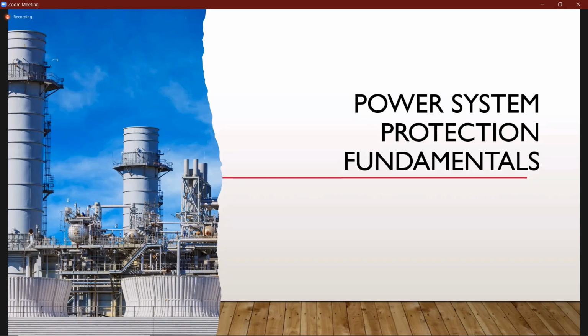We don't simulate faults in the middle in order to determine severity. It's really at the substation, or in other words, at the bus bars that we do that. So having gone through that exercise, you would now come to 5, where you are looking at the type of fault, and whether it was the double line to ground or the line to ground that was creating the largest fault, simply because of the configuration of the network.